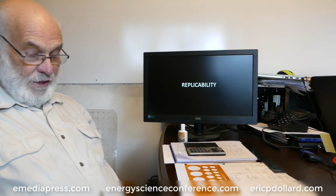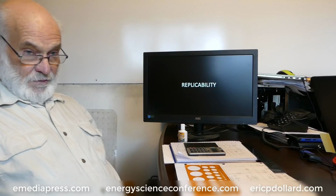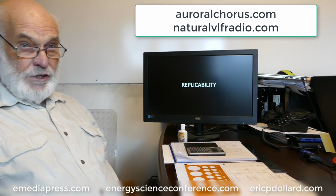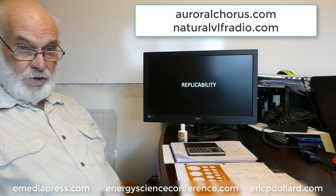You have to be able to build the necessary filter networks. You have to be away from power line harmonics, which is damn near impossible. They're getting stronger and stronger every year. But if you have some remote property out in the middle of nowhere and you can stretch out a good fraction of a mile or more of field telephone wire and a couple of ground rods, then the easiest thing to use is a Steve McGreevy device, because they usually have the filtering and the overload protection built in, and those are readily available.